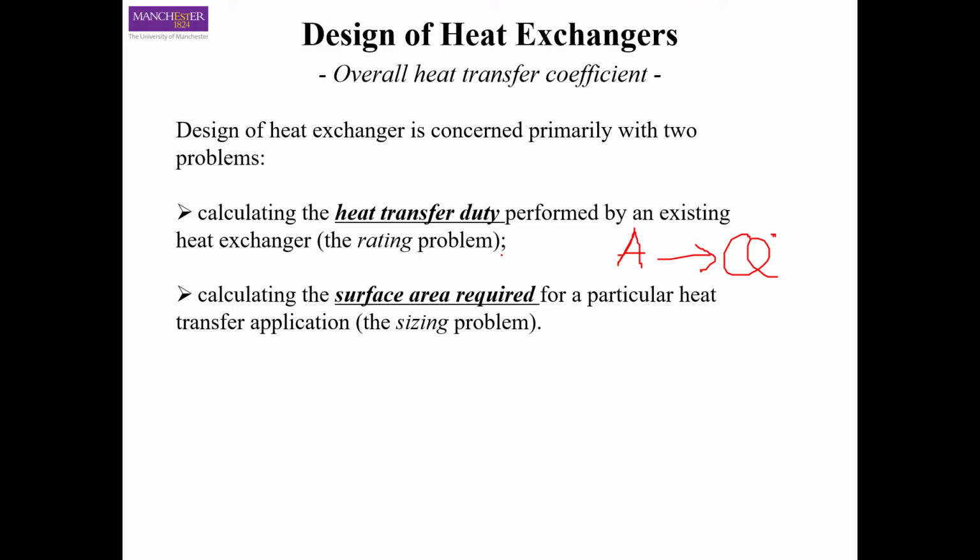So we are just rating the heat exchanger to see if it is going to work for a duty, because you might have changed the conditions of the process or you might have changed the temperature. So the duty of the process is different now, but you have already purchased a heat exchanger for the previous conditions, so you don't want to buy another one. You are looking at whether your existing heat exchanger is going to work in the new situation or not. That is what we call the rating of the heat exchanger.